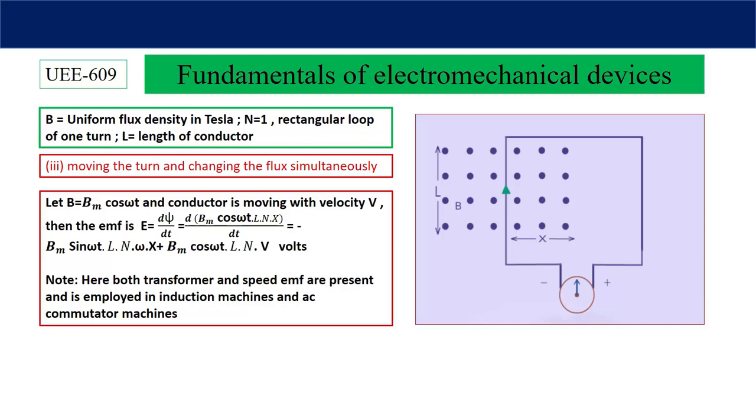Now, as soon as the EMF is induced across the rotor conductor, as per Lenz's law, the direction of the induced EMF will be to oppose the cause, and the cause is the flux linked with the coil, or changes in flux linked with the coil.